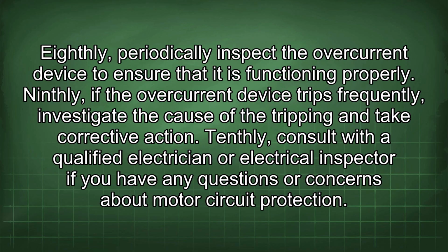Ninthly, if the overcurrent device trips frequently, investigate the cause of the tripping and take corrective action. Tenthly, consult with a qualified electrician or electrical inspector if you have any questions or concerns about motor circuit protection.